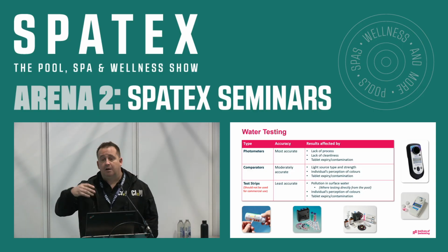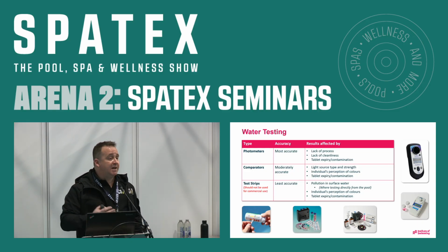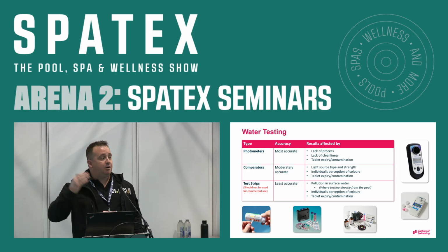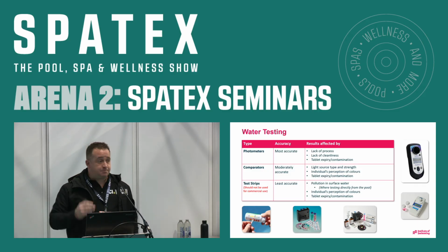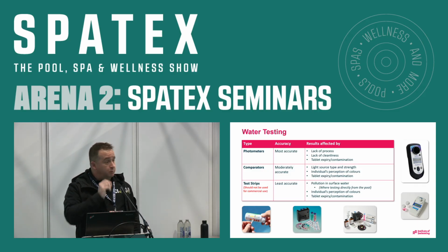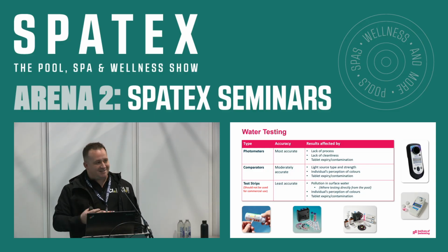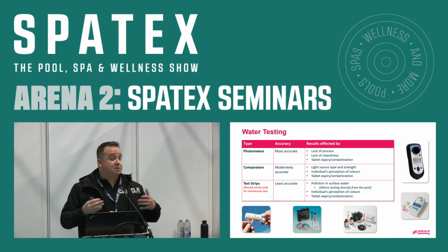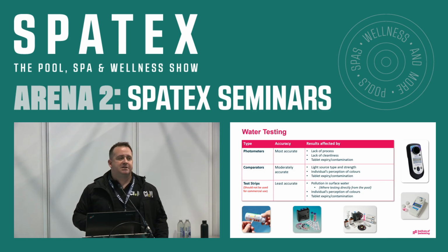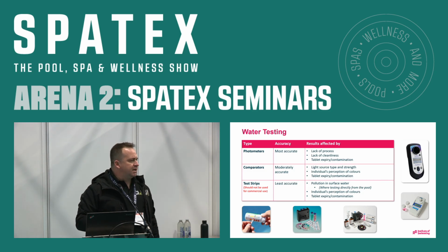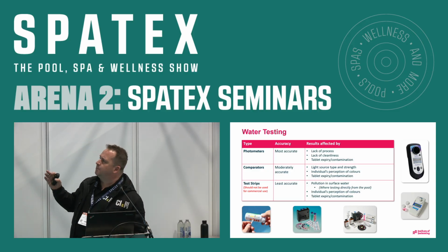Okay, I was lucky enough to have some training from the experts yesterday, right? And a point that was made very clear is they are simply measuring a colour of water. They don't know what it is they're measuring. They just go, yeah, that's pink, and pink on this setting gives me 1.5. Yeah, and so you have to give that piece of equipment the best opportunity to be able to do its job properly. Okay, coming down to, missed one, tablet and expiry contamination. Obviously our tablets, make sure they're in good nick, okay, make sure they're within the use-by date, yeah, so you don't have any problems from there.